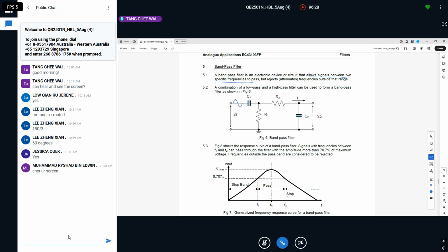So with that, we look at the circuit again. Now, of course, you expect to see more. Rather, you can see one low pass, one high pass. This one we just went through just now. This is a high pass, and this one you know is a low pass. Same thing, the input here and the output on the right hand side. So if you see both high pass and low pass inside a circuit like that, straight away you know it's a band pass filter.